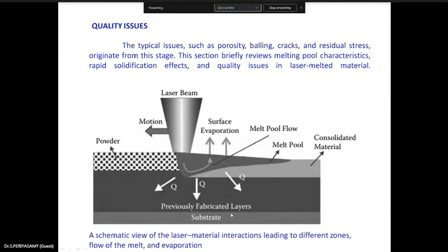So for the defects, whatever comes up, you have to consider all these things to nullify them. Then in-process monitoring of not only the geometric dimensions but also the surface quality of the finished layer. So continuous monitoring will tell you whether cracks are present or not, and then that will be rectified. Similarly, you have to check the geometric dimensions as well as the surface quality.